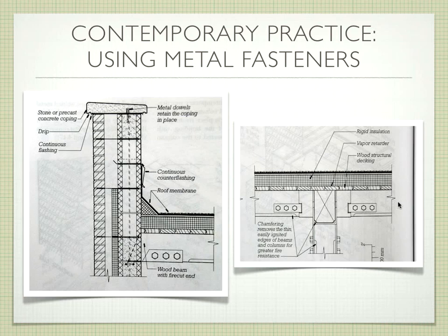The taper is still here on this beam, so if this goes to fail, it's going to fall cleanly out. The bolts are fine because the bolts are outside of the pivot point. The steel's just going to bend. Too much weight on the steel.